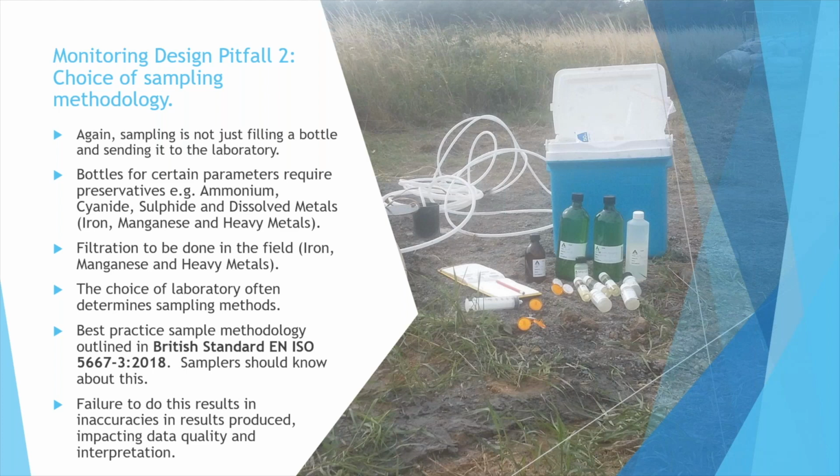They do not give you the field filtration and preservation equipment. Instead, they rely on the assumption that the sample will be relatively unchanged, and they can add acid and filter at the laboratory, and everything will be okay. But unfortunately, inaccuracies do occur through that route, and it can impact your data quality and the interpretation you make once you have that data.